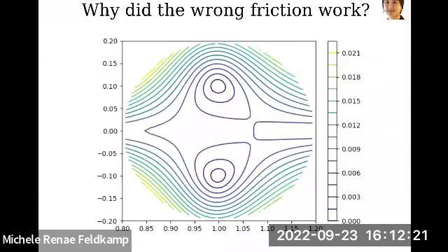What's the difference between the nearest viscous friction model and the Coulomb friction model? Turns out, thanks to what my student Yo-Yo calculated here, it's actually really small. So this is a relative error. It goes up to 2%, while the velocity changes by 20%. So if you're sliding under Coulomb friction, that's very, very similar to moving under viscous friction. So similar that the errors are pretty small.